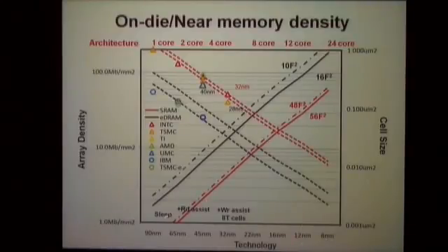So if you think about SRAMs, we started with a bunch of circuit assist techniques to help the scalability of SRAM. We started with sleep devices, with read assist, with write assist, and now we are moving to, for certain levels of the cache, the 8T cell, which is a variant of this traditional 6-transistor SRAM.